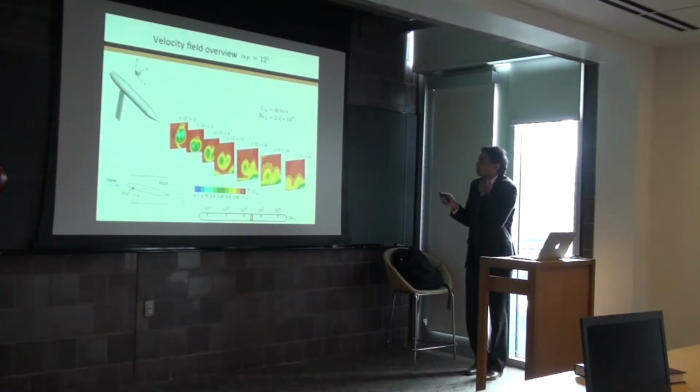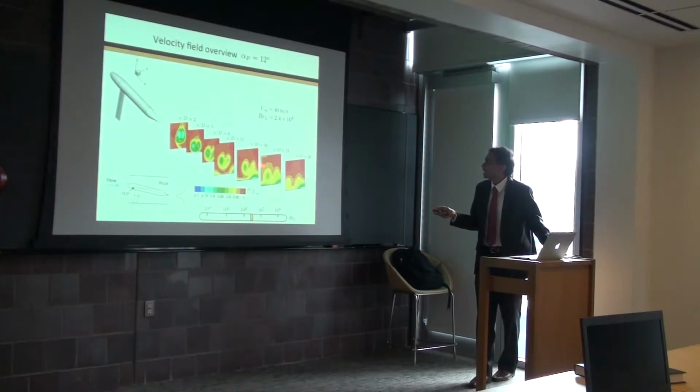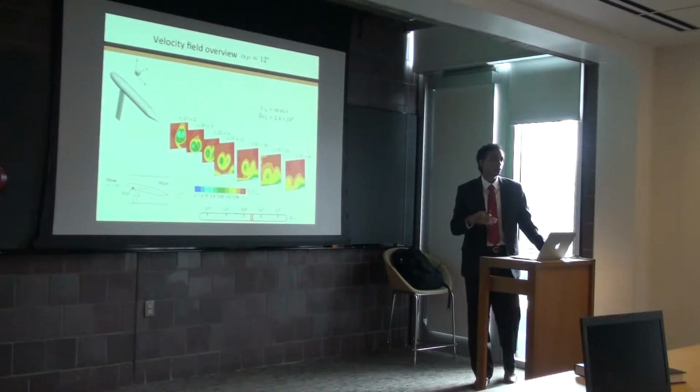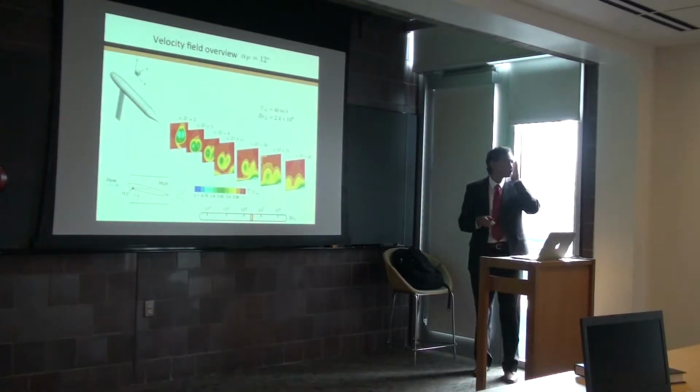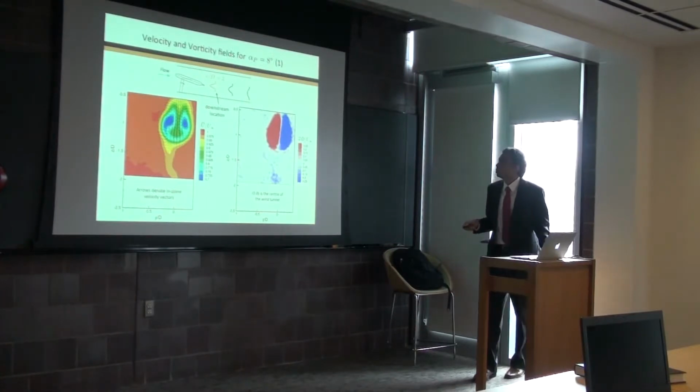Oh, and it's very important to note the limitation of the experiment as well. So look at the last 4 downstream locations here. The vortices that are shed at this angle are actually impinging with the boundary layer of the wind tunnel itself. And so this is kind of the limitation of the experiment. We can't really go beyond this pitch angle. So let's zoom into that.